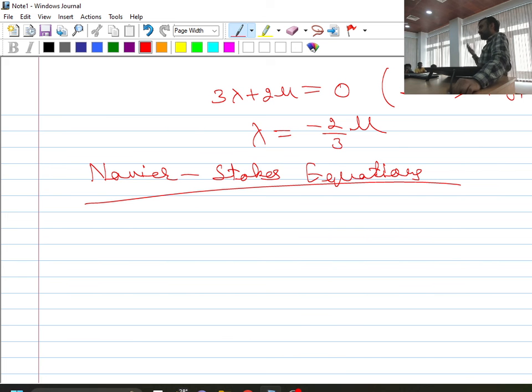Then we consider the Newtonian fluid. For Newtonian fluid we have supplied the formulations which represent the relationship between stress and strain tensor, and once we have converted that stress and strain tensor, we found some coefficients, and to determine the values of these coefficients, we have used some hypothesis that is called as Stokes hypothesis.